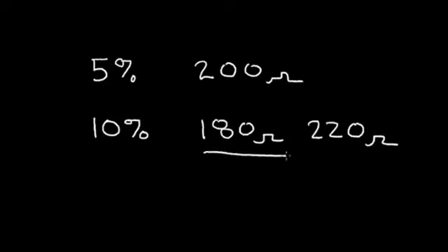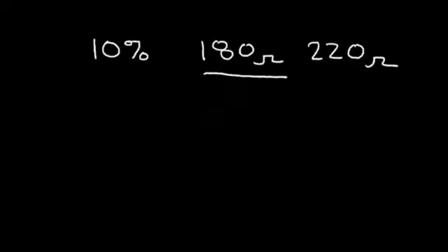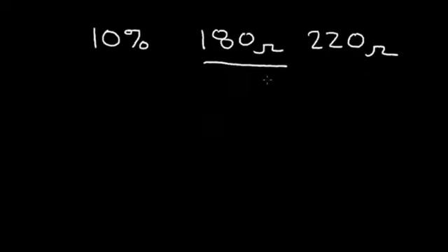So let's consider using 180 ohms. Am I going to exceed my 25 milliamps at any time in this LED? Let's say that I have this 180 ohm resistor, my light emitting diode, connected to ground. And let's say that the power supply can be 10% high. So instead of being 5 volts, it's at 5.5 volts.